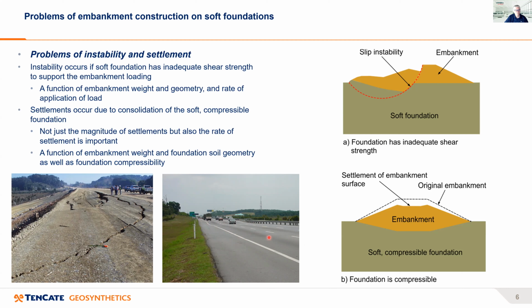And the key point about these settlements is it's not just the magnitude of the settlements that can be a problem, it's also how quickly, or the rate of the settlements, that's also important, as shown here in this bottom right diagram. And basically the amount of settlement is, again, a function of the embankment weight, and it's a function of the foundation soil geometry, as well as the level of compressibility. So these are the details we'll be looking at today.